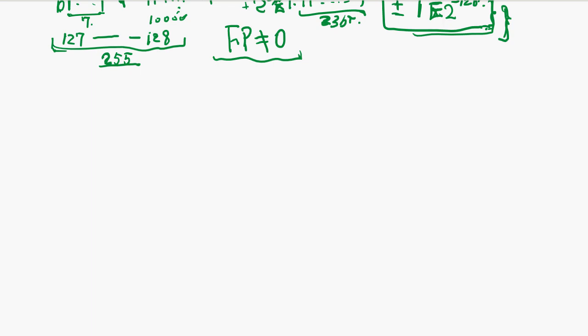But rounding to the nearest is a big problem in high speed floating point, because after you calculate, say you get the final answer X and it has some number below, and you have to round it. This rounding may cause carry propagation again.